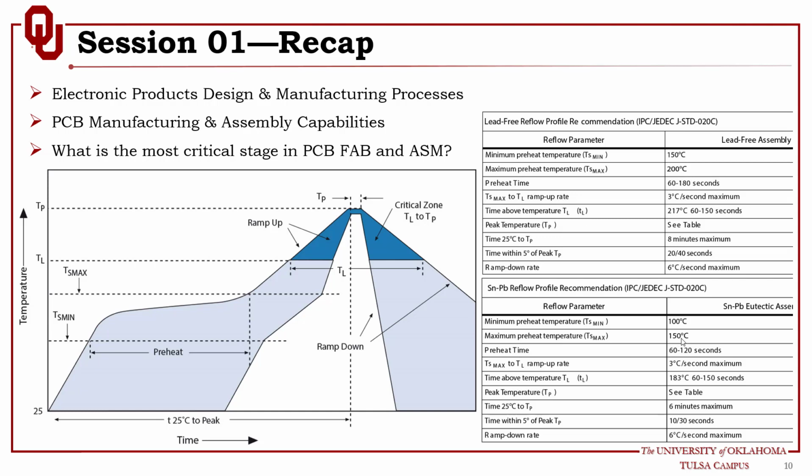Now the preheat time really takes time. It's between 1 minute to 3 minutes for lead-free. For leaded, it's enough to have 1 minute to 2 minutes. That's it. Now you have the critical point, which is the maximum temperature here, which is only 3 seconds. It should not go more than 3 seconds at this point.